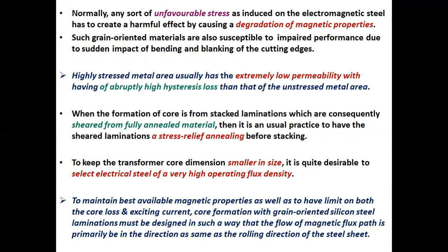Highly stressed metal area usually has extremely low permeability with abruptly high hysteresis loss compared to that of the unstressed metal area.